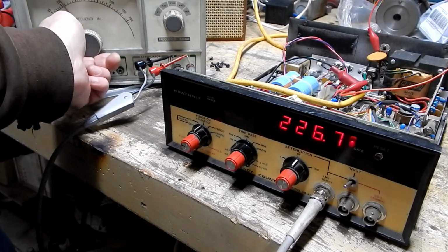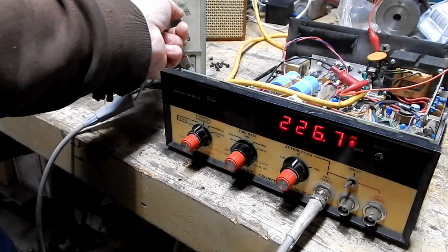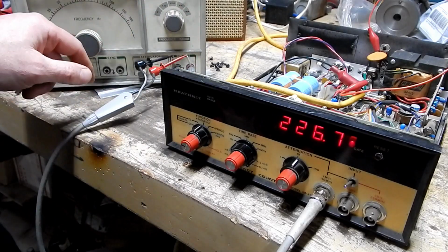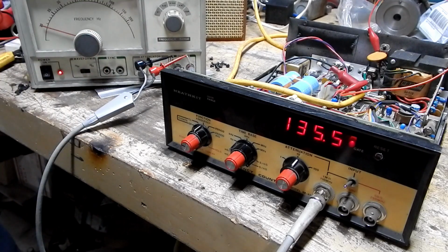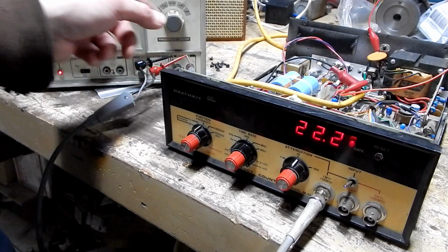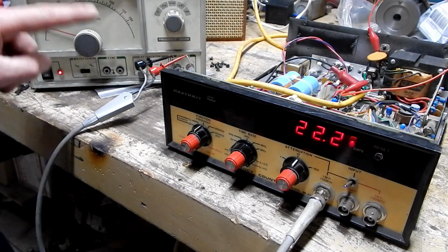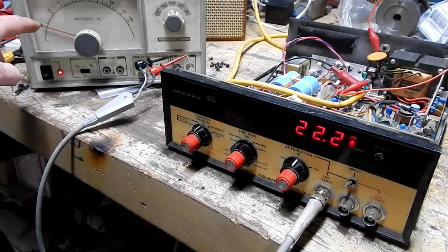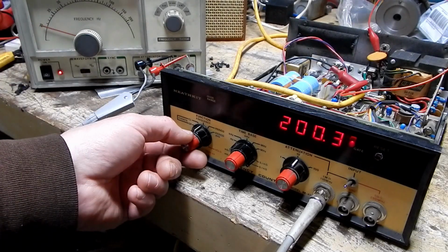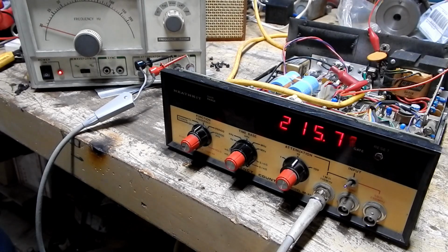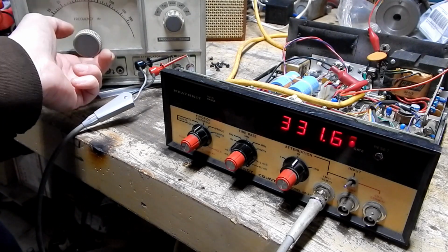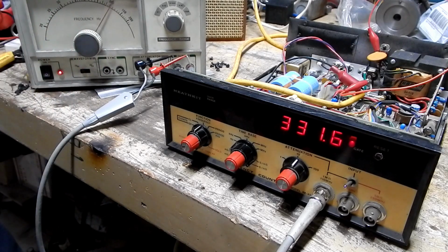All right, so now I'm going to bring this back down to the low end here, and bring it up to the times 10 range. So 20 times 10, now that should bring us up to about 2,000 hertz. Let's see, now that's saying 216. That doesn't seem right. Well, that does make sense because I'm at the bottom end of the range here. So that should come back to about 222. This should be around 300. 332.